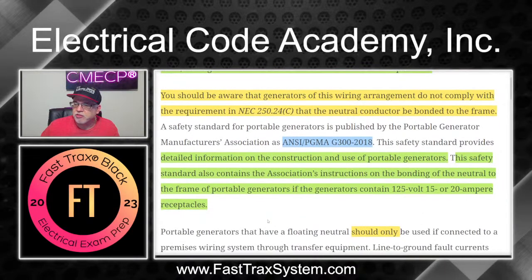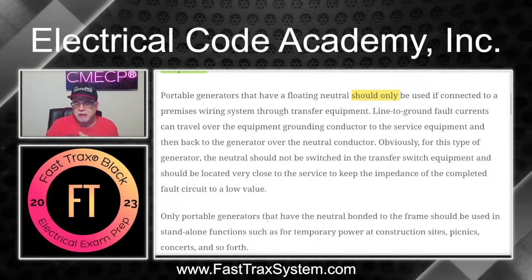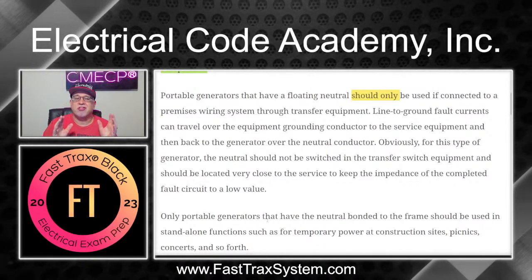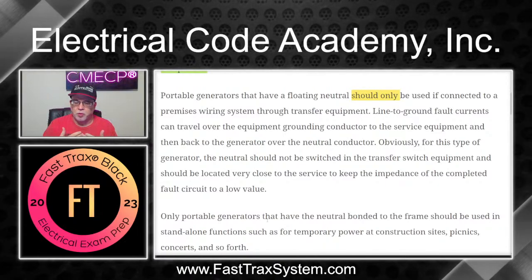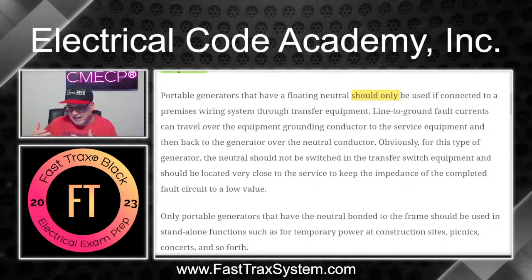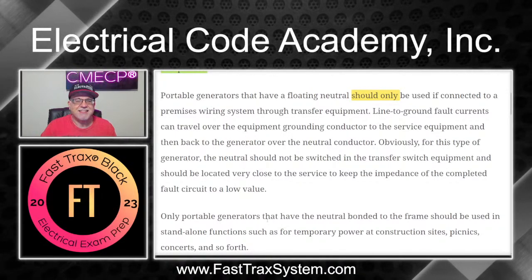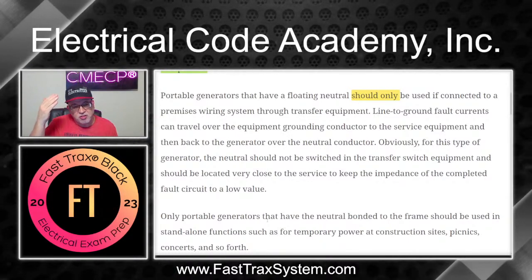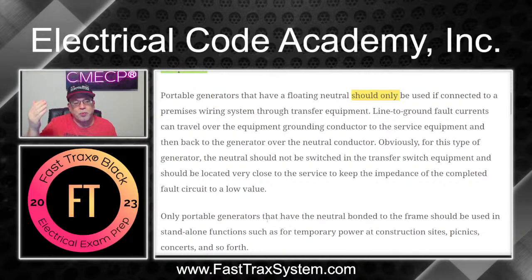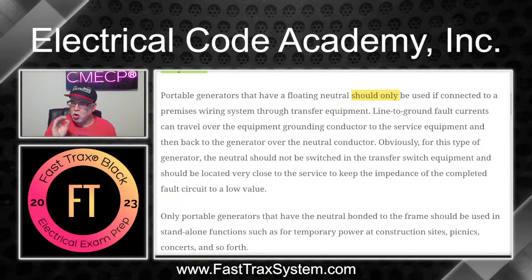Now, when it comes to generators, the only other thing I can tell you is you have to be careful because there's a lot of makes of generators. And not all generator manufacturers understand the difference and the importance of what they're selling their generator for. Most of the portable generators that you would see out there, you'd have to think they're being used in a portable application as a standalone, as a separately derived type system, right? And so if that's the case, we want to make sure we have that system bonding jumper in there, or that connection from the neutral point over to the frame. Okay? We want to make sure that takes place in those type of systems. But you got to be careful what you buy, okay? So you know what you're getting.